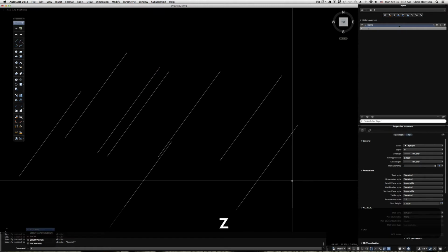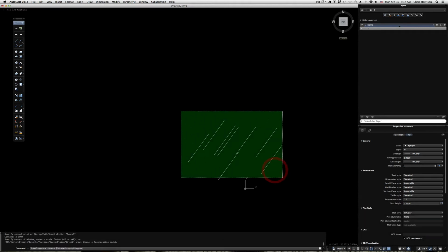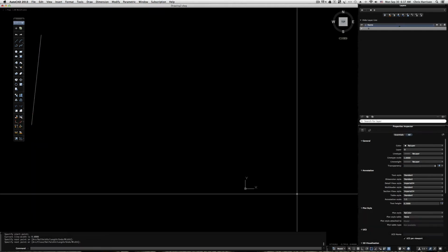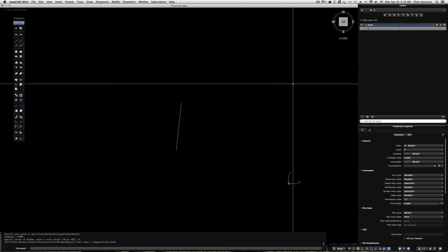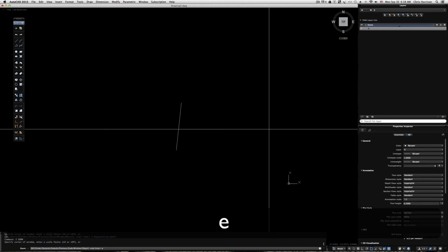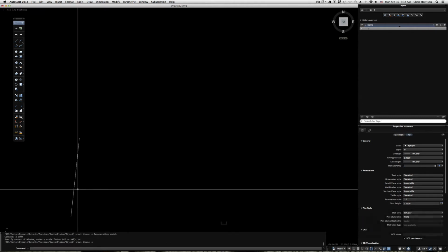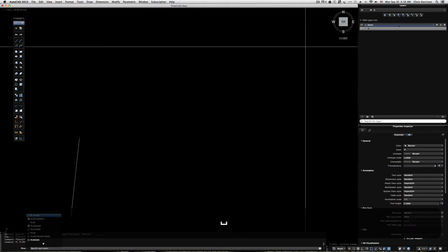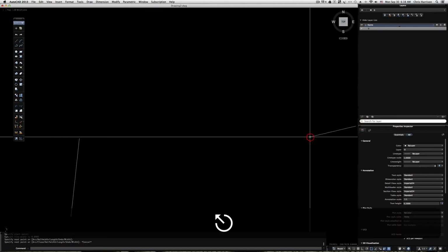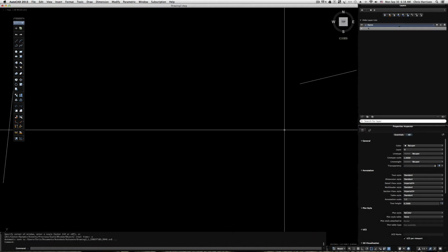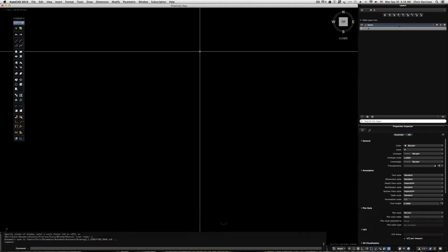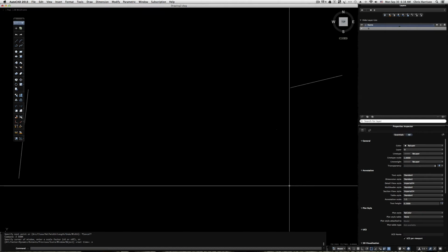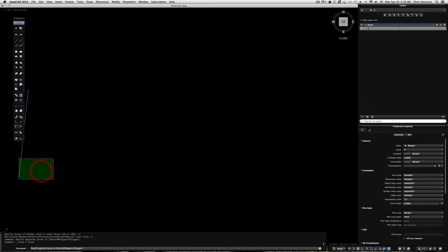Let me do a zoom, Z, enter, E, enter. Zoom extents brings, so say for instance I have something here, and as you see, if I type in zoom extents, it brings everything into focus. Let me do a zoom extents. Come here, just draw these separate lines. So when I hit zoom extents now, it brings everything on my page into focus for me. Okay, it's good to know.